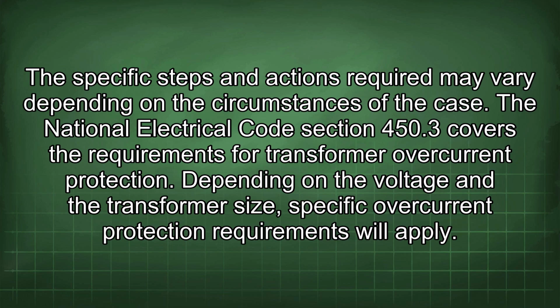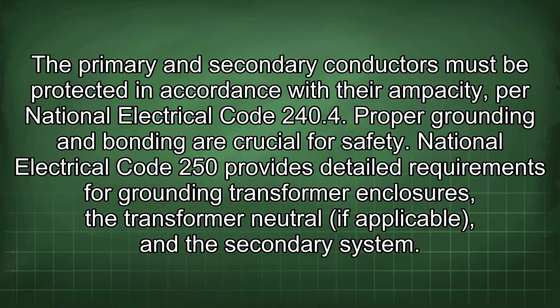The National Electrical Code Section 450.3 covers the requirements for transformer overcurrent protection. Depending on the voltage and the transformer size, specific overcurrent protection requirements will apply. The primary and secondary conductors must be protected in accordance with their ampacity per National Electrical Code 240.4.